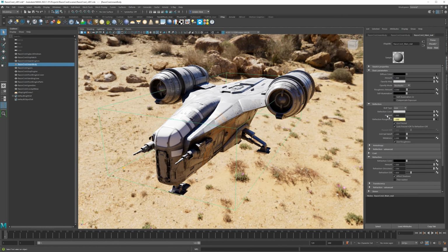One other thing about ACES is that because it is color correcting the swatches, it looks gray to you. But if we turn off color management, you can see it is white. But we want to have color management on. It's going to appear gray just because it's color correcting everything. So that's one slight annoyance with using ACES, it does make this a little bit awkward.